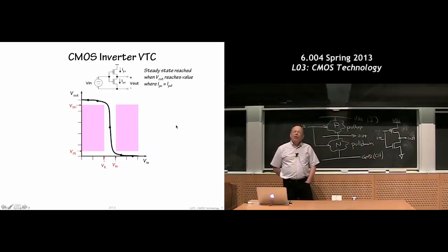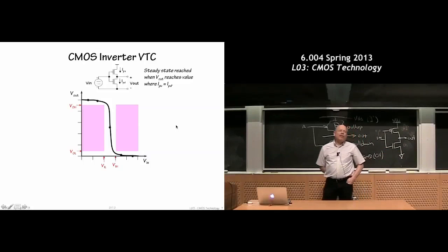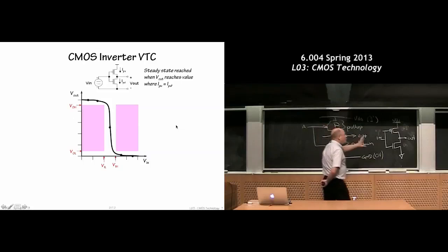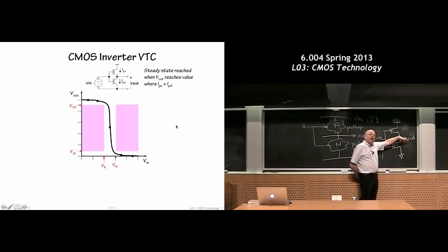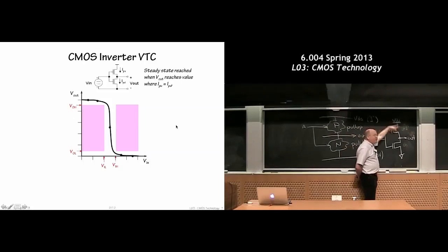What happens if they're both on? What can you tell me about the output? If I have a pull-up connection and a pull-down connection at the same time, there's a couple things. One, from a logical point of view, we probably will produce some sort of voltage in the middle, which is a forbidden voltage. In other words, we don't expect a logic output from this.